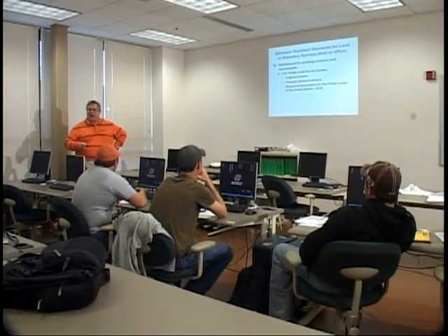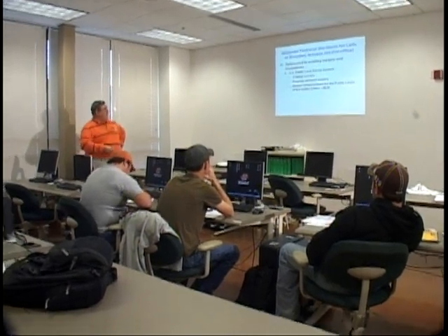It was a general land office, and that is a half-inch iron pipe located at that particular section corner. And we go over to the other corner and see that we found a GLO stone, General Land Office stone, at the southward corner of Section 5. So there we've referenced the existing corners that were the basis of our survey.